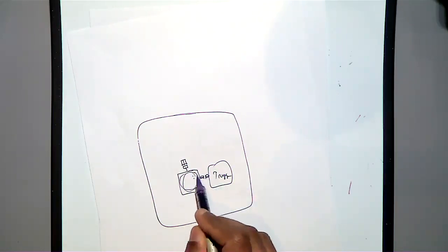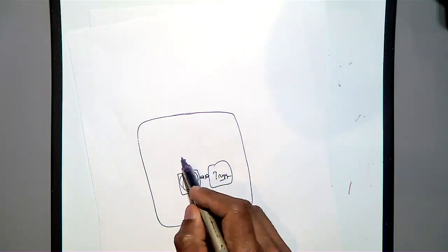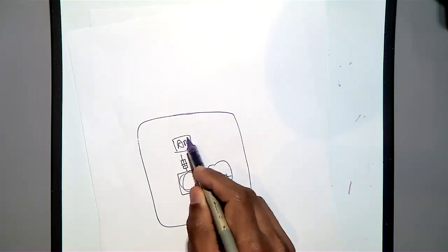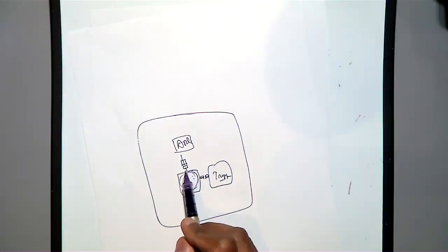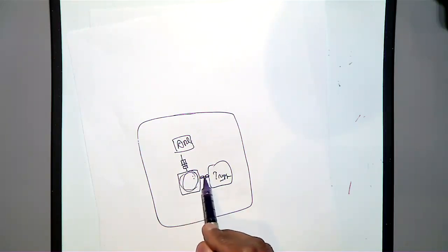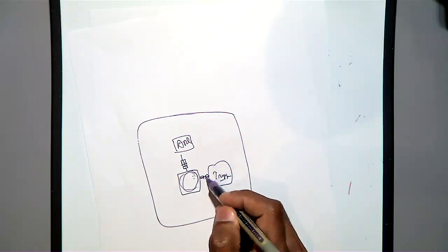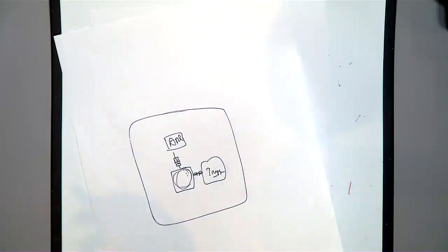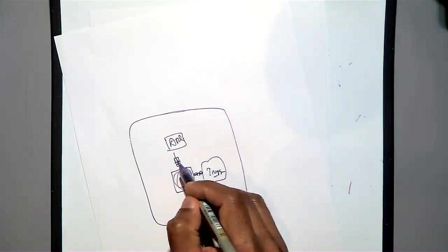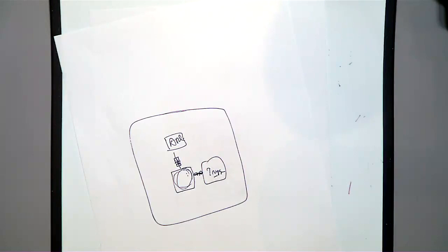You made this innovative block that is connecting to the trigger part, and then connecting to maybe the ADC part. If that is your innovation, then make sure that for the signal going to the ADC, you put a 0 ohm resistance footprint here, and here also a 0 ohm resistance footprint. Means after soldering, you will not connect your innovation part to the DSO first. You will test and make sure that your DSO is working. If it is working, then you can short these two and then short these two, so that your innovation is introduced. Otherwise, I have seen previously, they messed up the DSO design because the innovation went wrong.